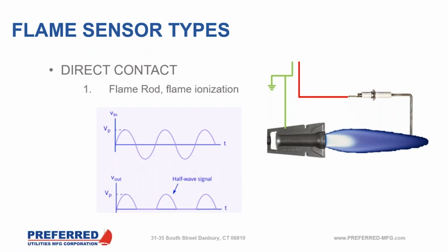And what's nice about this type of product is if, for instance, somehow the two lines going out to ground and going out to the flame rod were shorted, we would be able to tell that that's a short and fault. The flame safeguard would recognize that and would shut down on a failure, indicating that there was an issue.